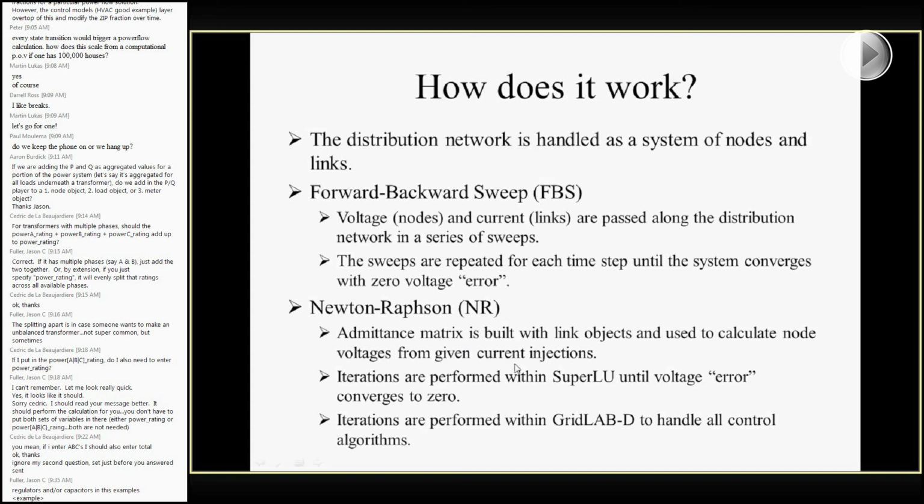Just a quick little note here, if anybody's familiar with the SuperLU project, that is what we are using as our matrix inversion utility inside GridLAB-D right now. There are provisions for hooking in external ones if you have a different preferred matrix inversion technique for the Newton-Raphson method.